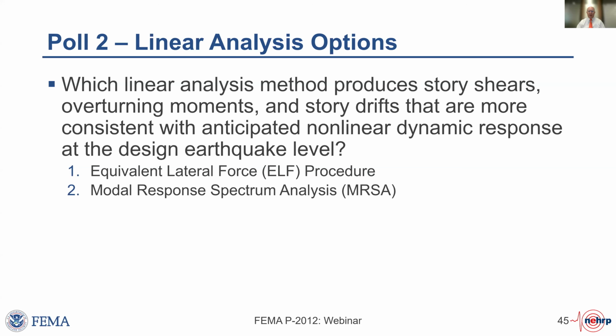ELF produces results that are more consistent with the envelope demands from a nonlinear dynamic analysis. So, I mean, on one hand, I guess you could say that the framers of that method who developed it initially did a good job when they were trying to do some enveloping. And perhaps we fooled ourselves by doing more complicated analysis with modal response spectrum analysis, thinking that the answers were more accurate, and that's not necessarily the case.